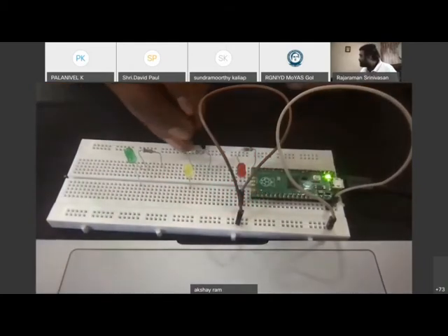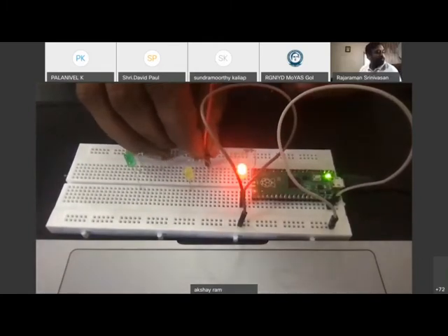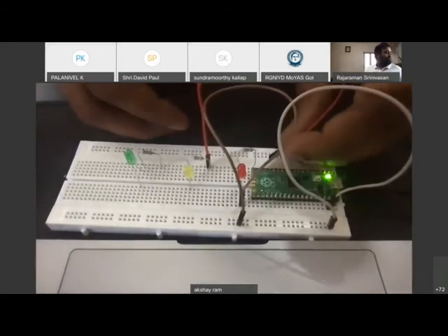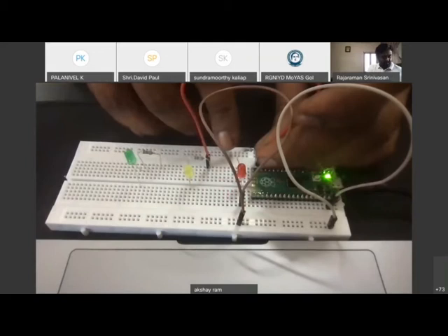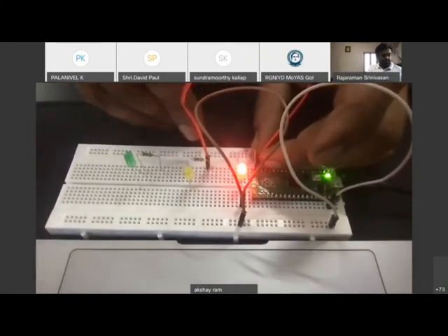So now this entire row is part of this resistor from this end of the resistor. So now we will plug the amber light onto pin 14, which is one above pin 15. Pin 15 is this one where the LED is glowing, which we had used last time.